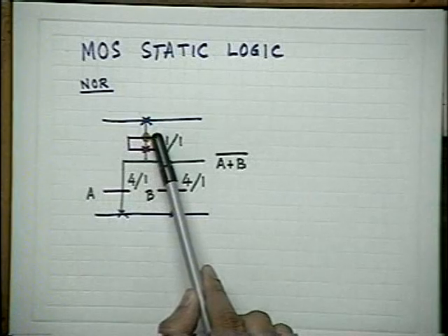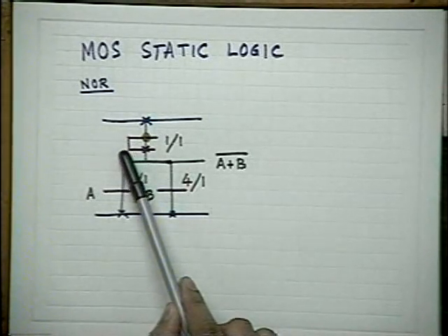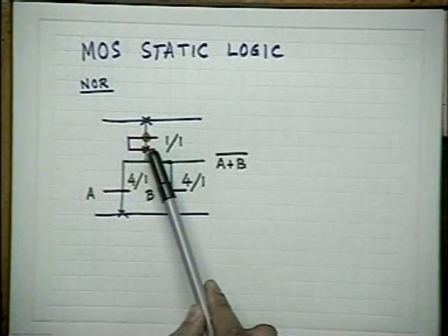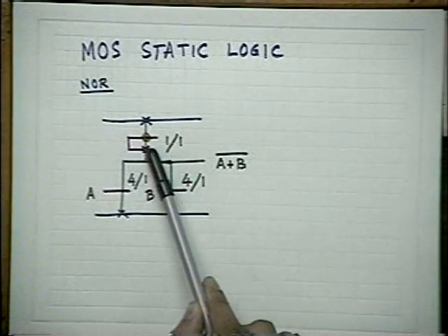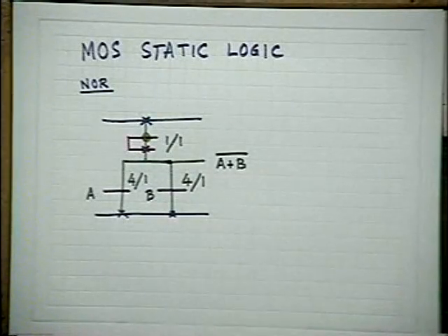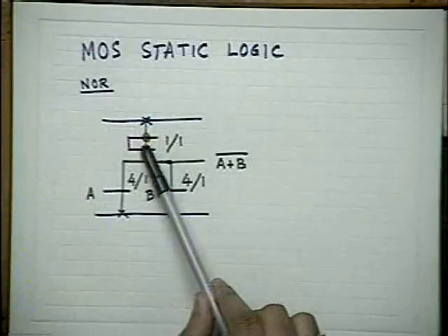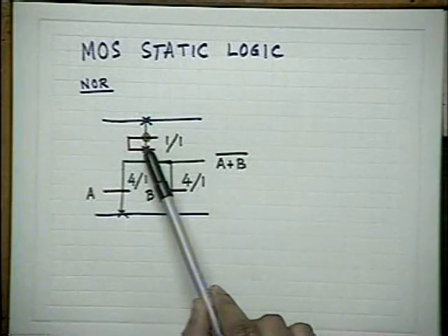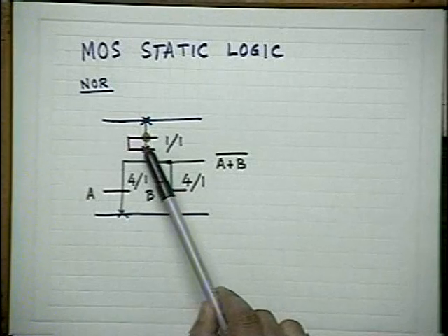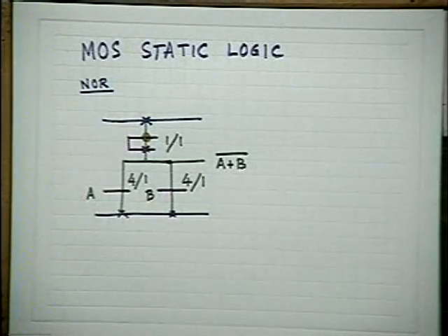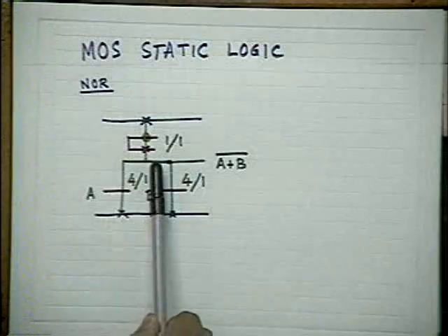And that is why this red line, the polysilicon, is intersected with a cross here. Of course, this cross should have been in one other color, normally black. In fact, all the crosses should have been indicated in a single color, usually black, but this cross indicates there is no transistor. If there is no cross, it means that at the intersection of poly and diffusion there is a transistor. But if there is a cross, it indicates there is no such transistor; poly and diffusion are simply interconnect levels, and they are connected at that particular point.